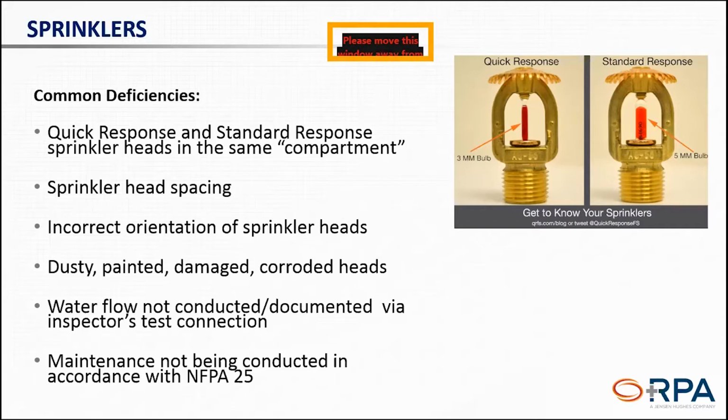So, you can have mixed quick response and standard response heads in a given smoke compartment if they're separated by a room or a door or maybe even a soffit. If you have a different height ceiling, you can potentially consider that a different compartment. So just be aware that just because you have different response heads in a given smoke compartment doesn't necessarily mean you're mixed. So just keep an eye on that.